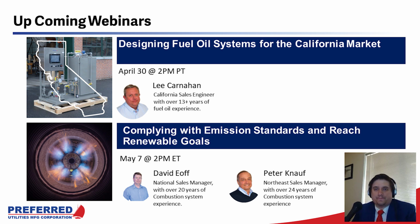Yeah, and another example of that is we paid a bunch of money to have our fuel handling systems shake tested so that they could meet OSHPOD requirements and go on the roster in California. And we did it to our standard design. So we ended up taking that OSHPOD California earthquake preparedness language and putting it into our master spec for everybody, because it doesn't hurt and it doesn't cost any more. So why not get a fuel handling system that's earthquake rated, to California standards?